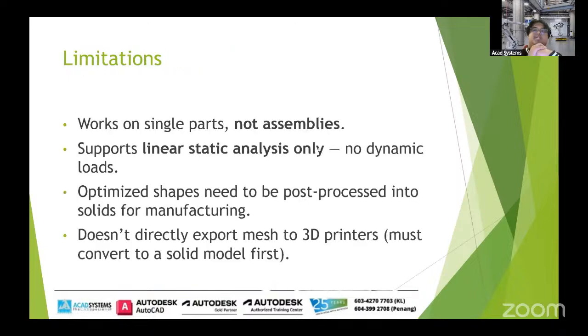So here are the limitations when it comes to the shape generator. It only works on single parts, not assemblies. So this is a very big one.